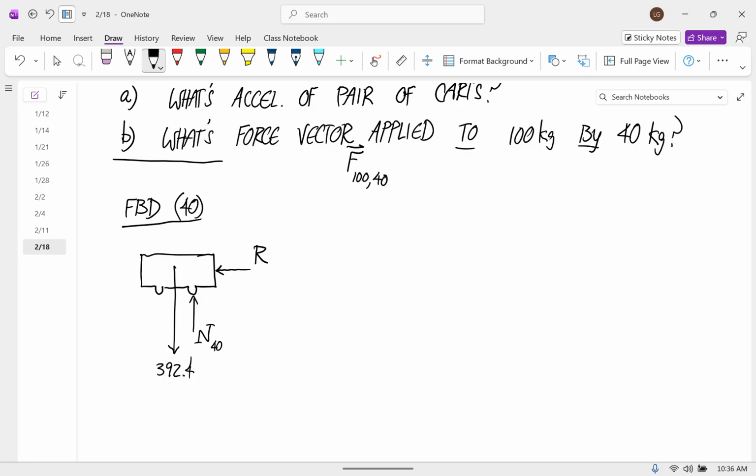So basically, there's nothing wrong about this. It's just that we're not going to take the next step and figure out what moments these forces are applying. We'll get to that when we start talking about rigid bodies. So I think I would just get in the habit of applying those forces where they actually act. Why do this kind of problem differently than what we're going to do when we get to rigid bodies? Remember that the weight force has to act at the center of mass.